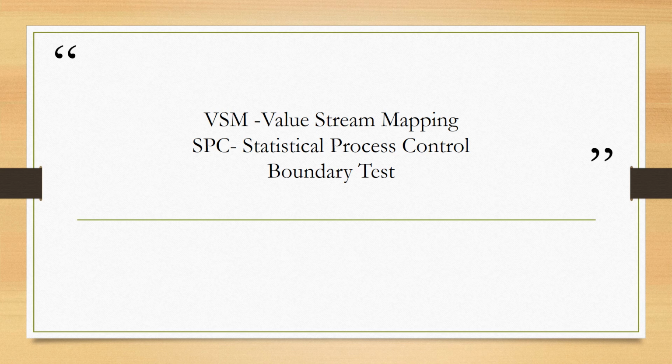One of the most important steps implemented was the boundary test, and this test is done at the start and end of every shift, mainly for inspection machines like penetration inspection and x-ray inspection, where samples of specified defective parts and standard parts are sent, which ensures that the sensors are working properly, which can decrease the rate of reworks and manual inspection.